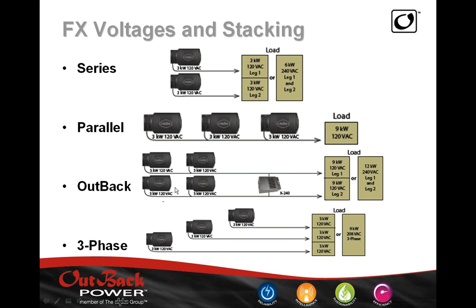And as an off-grid system, and I failed to mention this here, for off-grid systems, you can have up to 10 inverters. So you can have up to 3 inverters per phase, or one of the phases can have 4 inverters, and the other 2 phases can have 3 inverters. But essentially, for a grid interactive system, you can only have 1 inverter per phase. That's kind of important to keep in mind. And we are going to be overcoming that issue pretty soon.